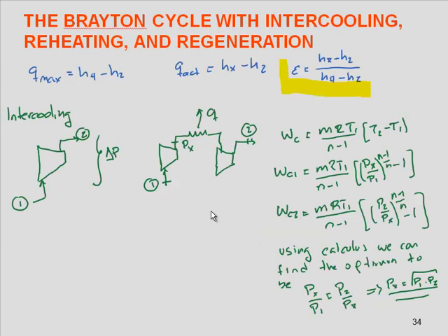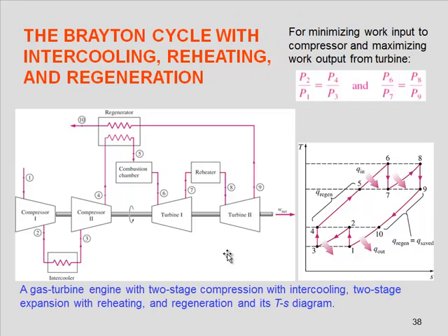Usually this intercooling reduces the work of the compressor, but does not increase the efficiency, because as we can see here, we are increasing the amount of heat that we need to provide.